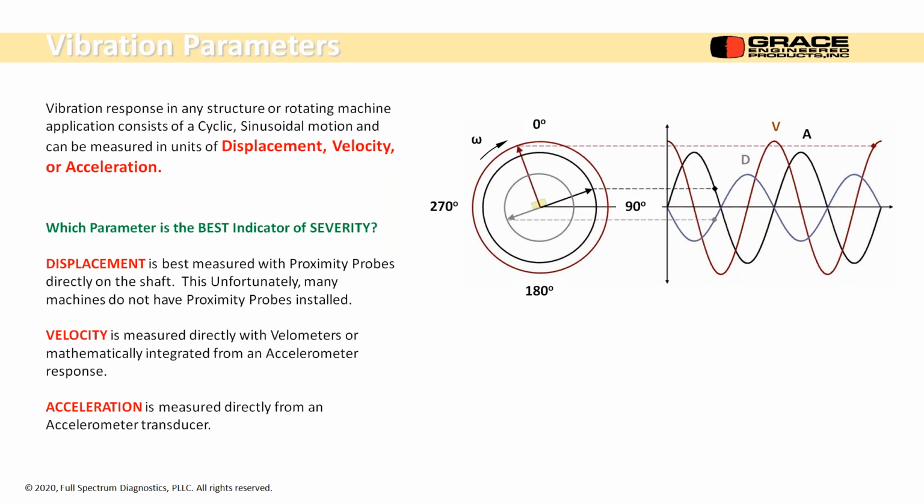So what the probes are for, they are inserted through the bearing housing, and they come really close within about 50 mils of the shaft, 30 to 50 mils. And they have a magnetic flux that changes with shaft motion. So they're able to detect thousandths of an inch, really tiny measurements, tens of thousands.